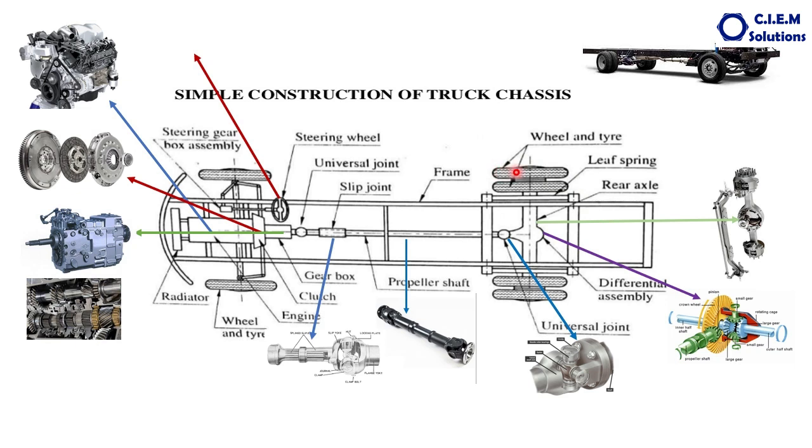Axle shafts are over, wheels are over. Next, the controlling devices. This is the steering wheel. This complete linkage is the steering mechanism. This is to negotiate the turn depending upon the road conditions. So this is the steering mechanism, which looks like this. And the next one is either to slow down the vehicle or to stop the vehicle depending on the driving conditions. The brakes are provided to all the wheels. This is about the brakes. And the steering, brakes, operation of the clutch, operation of the gearbox, everything is under the control of the driver.